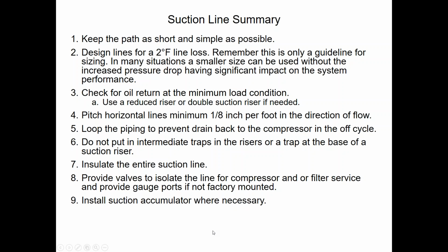Gauge ports, I wouldn't put gauge ports in. Most of our equipment already has gauge ports, so there's really no need to put additional gauge ports into the suction and liquid lines that are field installed.